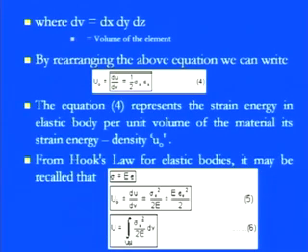With that consideration, since there is a linear relationship between the stress and strain, directly proportional, we can simply replace this equation in that form. So U0, which is dU by dV, can be replaced by sigma x square divided by 2E, or since sigma is equal to E into epsilon, as we saw in the previous derivation, we can replace it with E into epsilon square by 2.